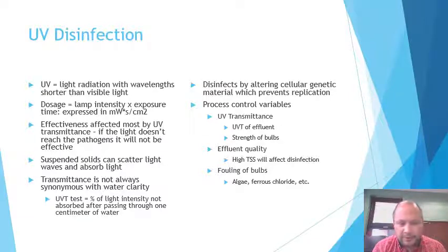Also, it depends on the transmittance of the water. Transmittance of your final effluent has to do with how much light can pass through it. Transmittance is not always synonymous with suspended solids. There are particles in the water that are not going to show up in a suspended solids test that can also absorb some of that light intensity and not allow it to come into contact with pathogens.